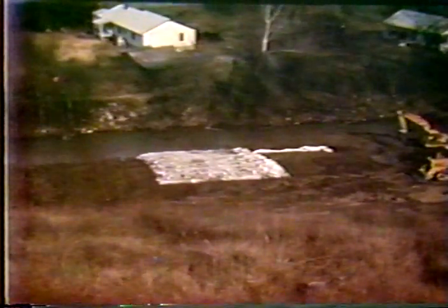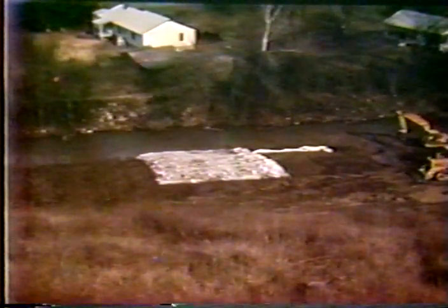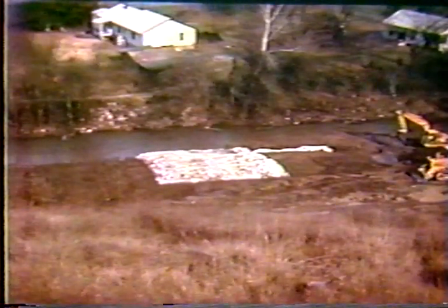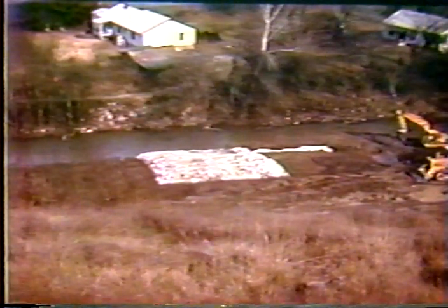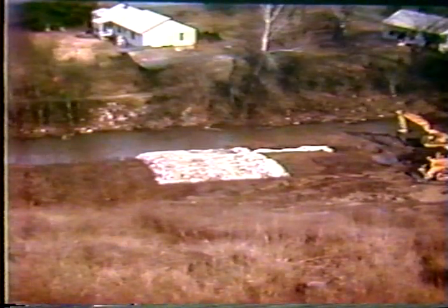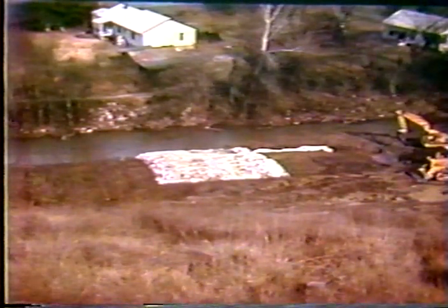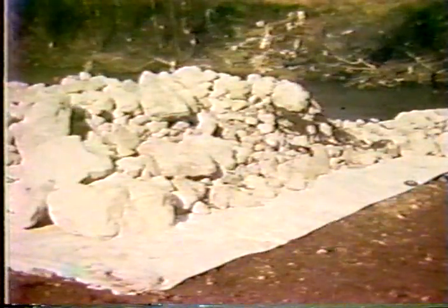An example here in this slide of a drainage blanket being installed. You note there on the monitor that the material's been excavated and they're putting in a drainage blanket. Just another illustration of an example where a drainage blanket might be constructed before the slope's flattened. Notice they're putting a geotextile down on the clay soil there and then installing the stone. Another view of that, a closer view.